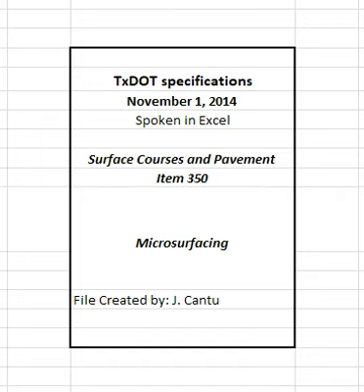4.10 Production testing. Control the production process within the operational tolerances listed in Table 5. Provide access to the mixing unit discharge stream for sampling purposes. Suspend production when the engineer's test results exceed the operational tolerances. The engineer will allow production to resume when test results or other information indicate the next mixture produced will be within the operational tolerances listed in Table 5.